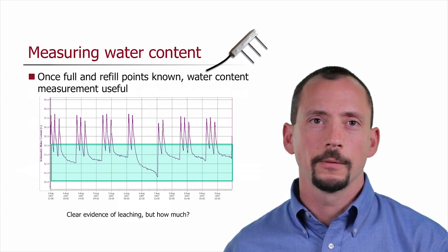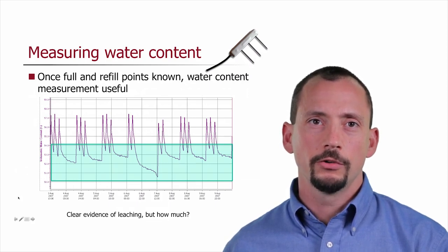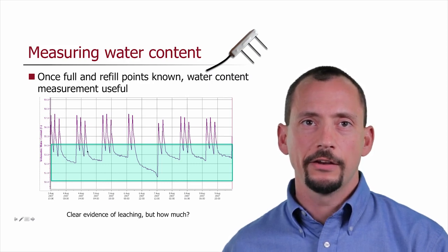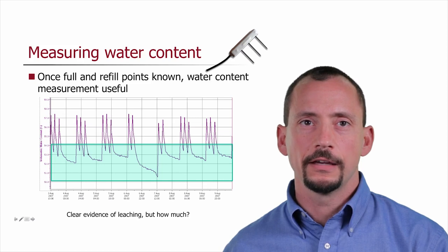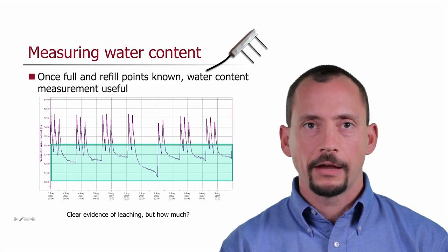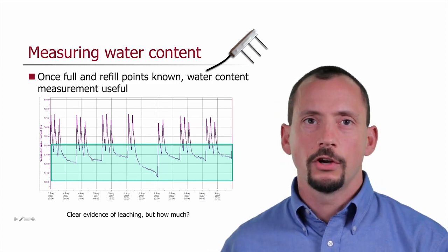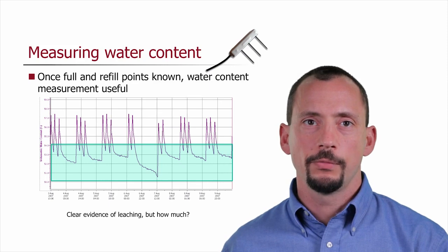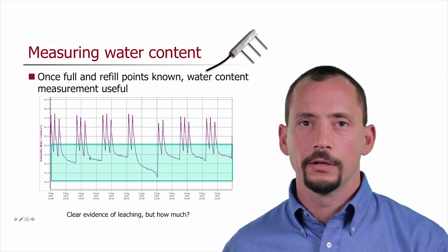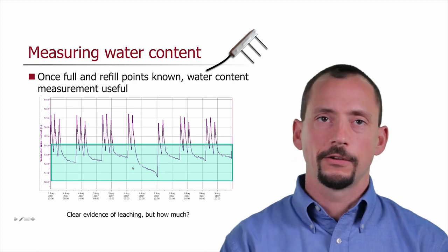Let me get the mouse here. You can see that as the soil drains down, this is water that's being lost from the root zone. Eventually that drainage starts to level off, and this is what you could identify as being pretty close to your field capacity. And so you really would want to only irrigate up to this level, and let your soil drain down, and the plants pull the water down significantly lower than that.